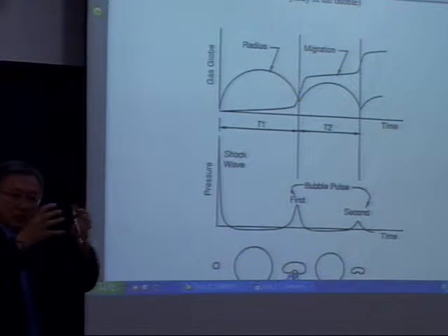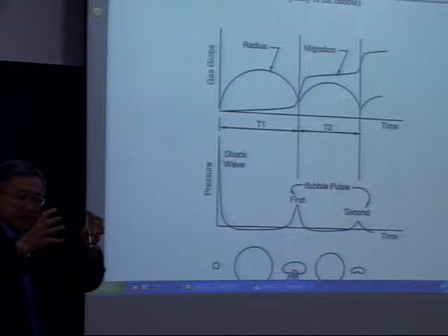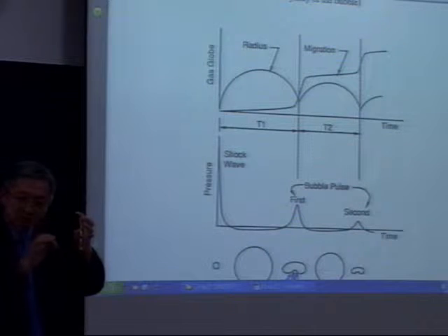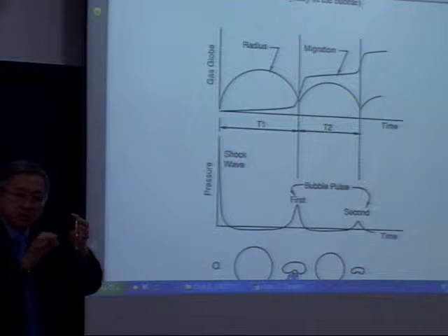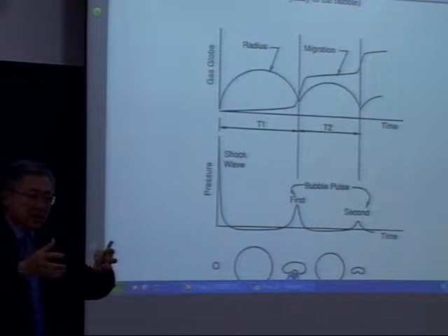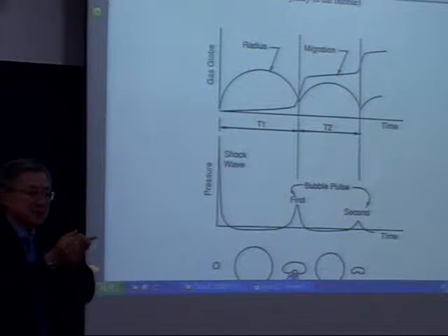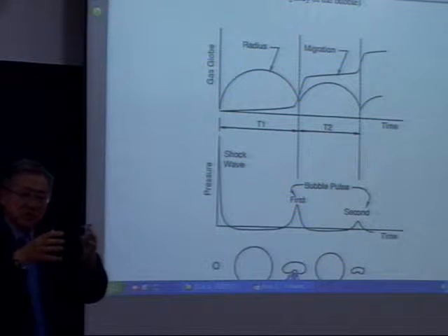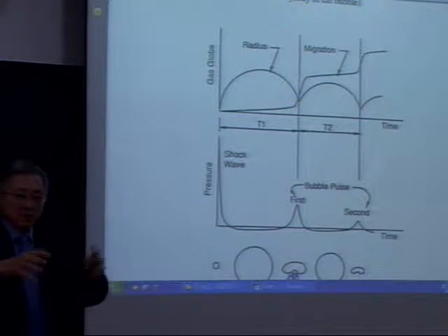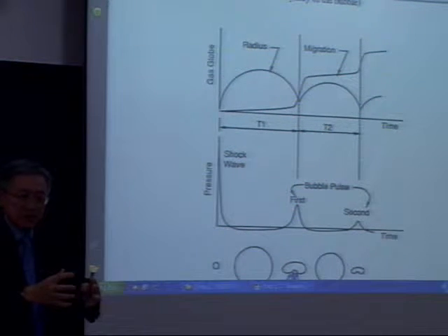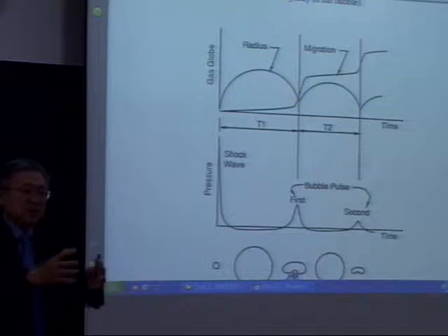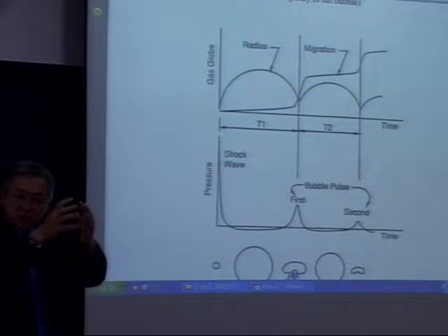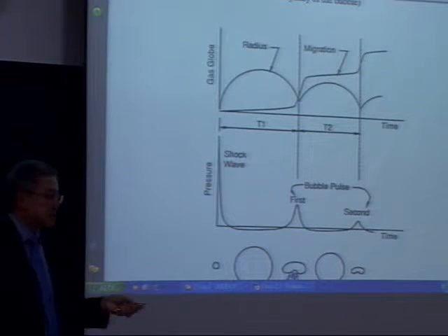The gas product is all still in there. As it gets down to the minimum, it loses balance because of the pressure differences at top and bottom. Then it collapses. But the gaseous product, with energy, is still confined in the water someplace, and it will keep migrating due to the buoyancy effect, toward the free surface.